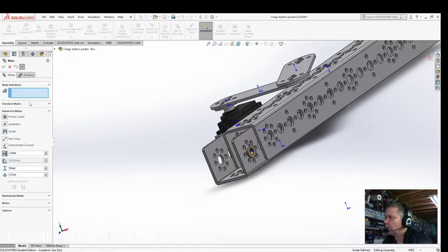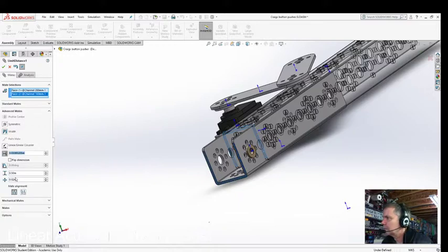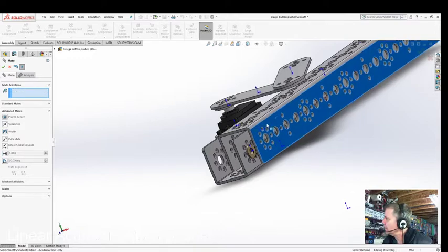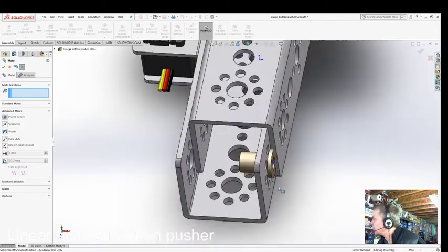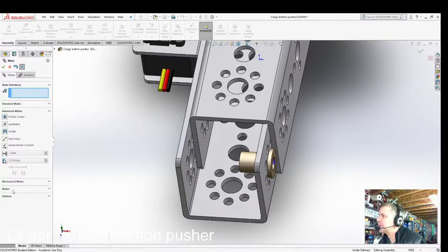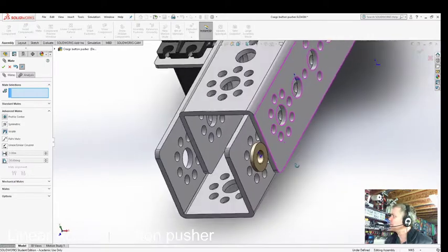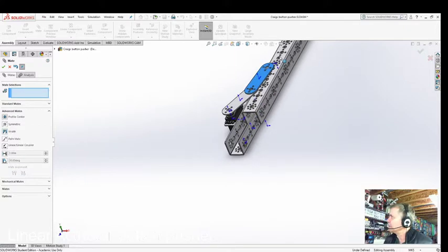Okay, and we're going to choose our surfaces. So it's going to be between this one and this one. All right, and we'll say yep. Now theoretically, this thing can only go in 2 centimeters. Now it looks like it's actually bumping into my bushing a little bit, but I'm going to just forgive myself. I could have probably stopped it a bit later by playing with that second number, the minimum number, I could have fixed that. And if I stretch it out all the way, it's never going to get to 50 because this arm doesn't go long enough. There we go.